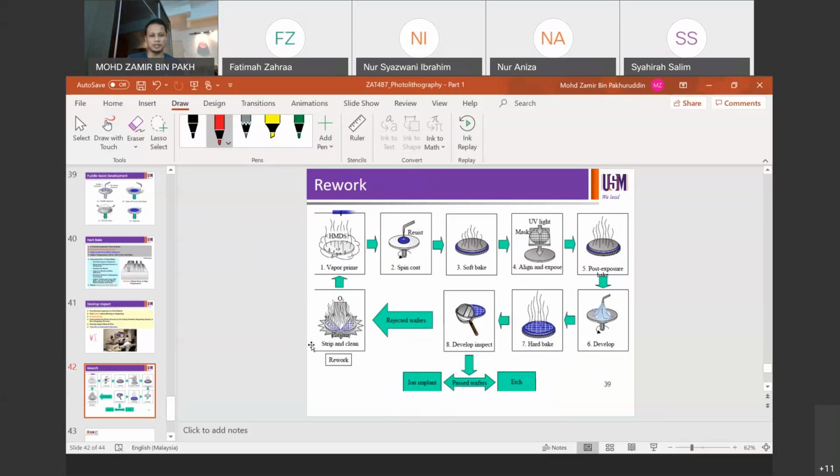So you can see from this illustration, we have priming, spin coat, baking, and so on, and then you finish the development spec. Under the visual inspection, you found out that there's some problem with the exposure process. Maybe the line is not small enough as in the spec, or you have defects, or underdeveloped or overdeveloped resist, or something weird. Then you have the privilege of reworking the wafer. It means you strip off the resist, go back to the first step in lithography, repeat the exact process, and then verify again at the VI step after the process.